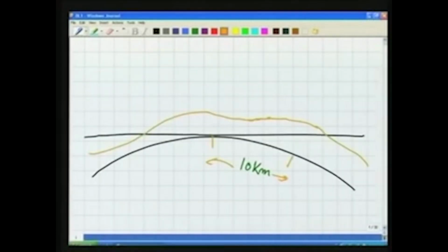I will give you one more example. Here is the earth, as you can see, that is the surface of the earth, and this surface here is the geoid, and here is a flat plane which is tangential to the geoid at this place. Now, in this example, let us say we measure the height of the points, point A and a point B, from the flat plane or the horizontal plane. By projecting these points here, we will measure these heights. So, what we see in this case, the height of A is more than the height of B from the datum.